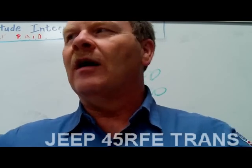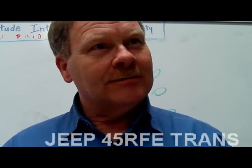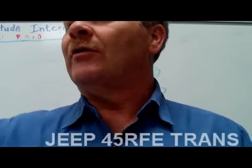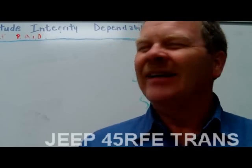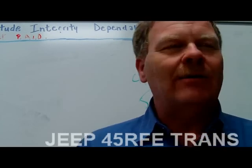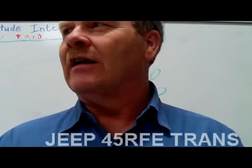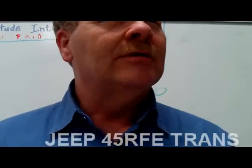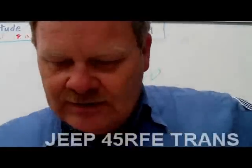You have to reprogram all the windows so that it will know where they stop and start. And once you get the windows reprogrammed, now the sunroof will work. But the sunroof wouldn't work until you programmed the windows, because we had the battery cables off longer than 15 minutes or something like that. But that was not anything you had to do with a scan tool. You just had to know how to operate your switches to program the window so that it could find where the bottom and the top was, because you've got smart motors. It's not just a reversible DC motor. There's more to it than that now.